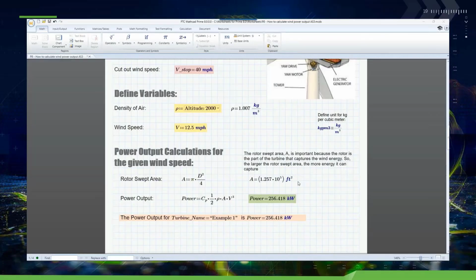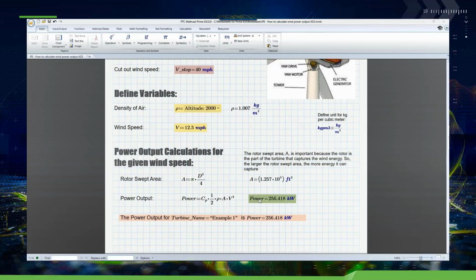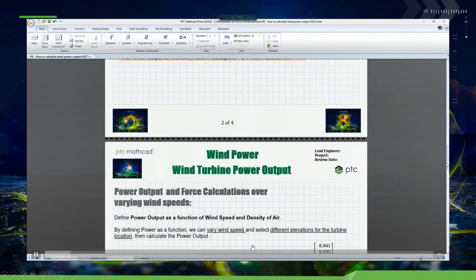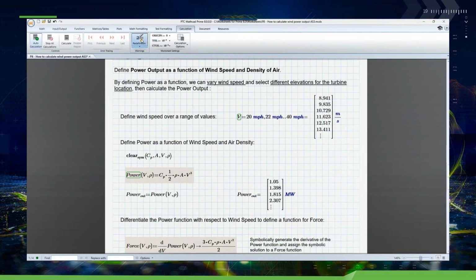I have a short video here just to take a quick look at these updates in the product. For the redefinition warnings, here is V and power. V and power have been defined as variables, and here they've been redefined, one as a variable, one as a function. So we have green notifications on them, which you can turn off in general, or you can turn off specifically by looking at the user-defined scalar variables and turning those off. But we leave them on because they're not an error, and it informs the user you've redefined this identifier in the worksheet. Likely you did it on purpose.